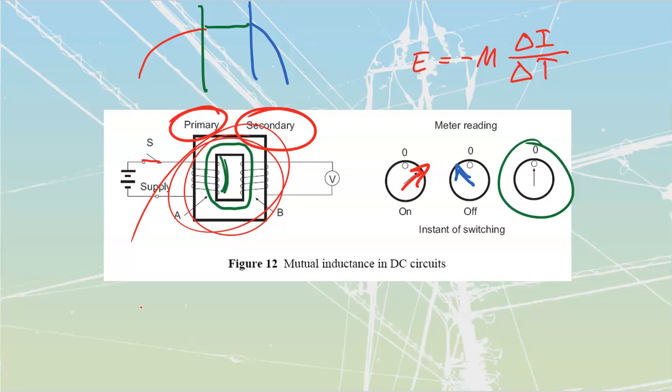Well, what we had over here is what we refer to as a pulse transformer. It's not being used as a transformer because it's a DC supply over here. We'll cover transformers later. It is transforming, but it's only transforming on the shoulders. In other words, we only get voltage out either when it's rising or when it's falling. So on this side over here, we're only getting any sort of recognizable signal at those points.